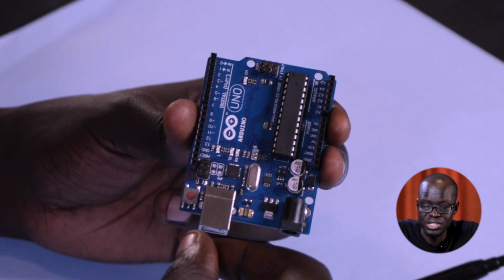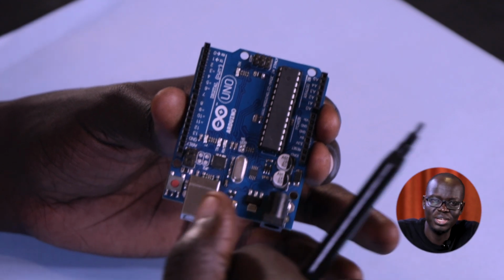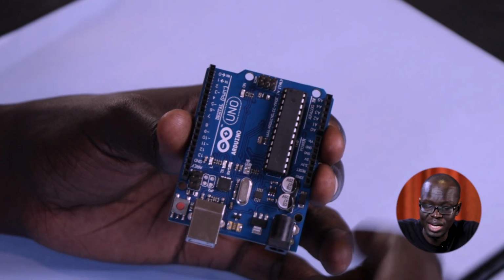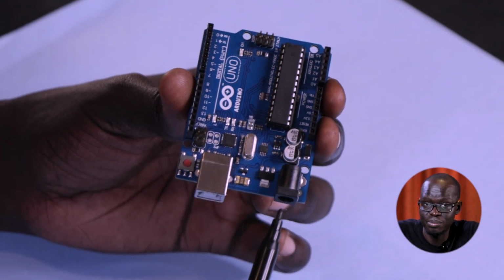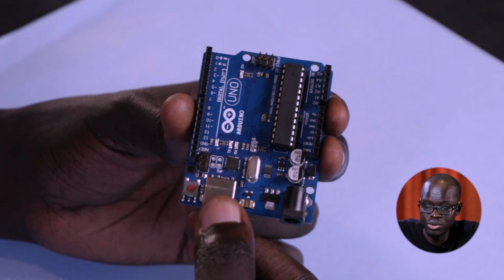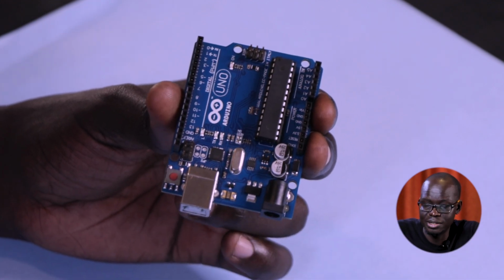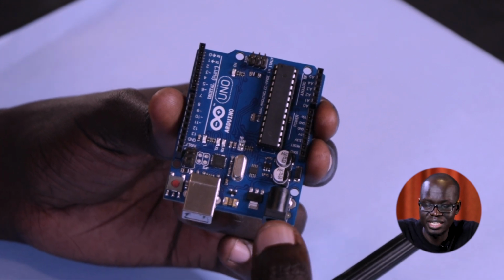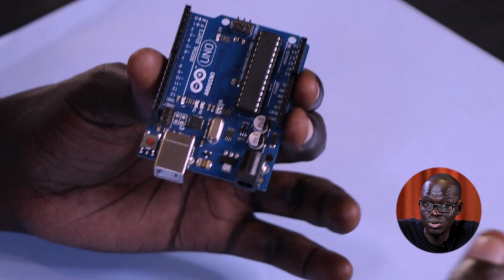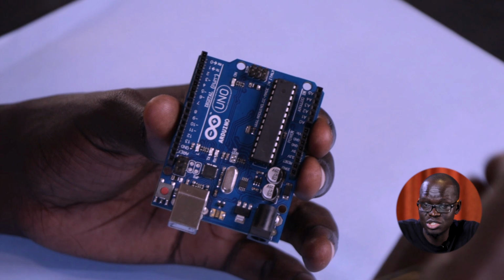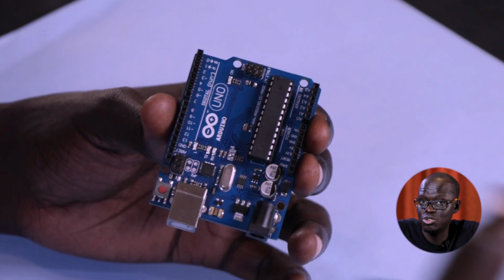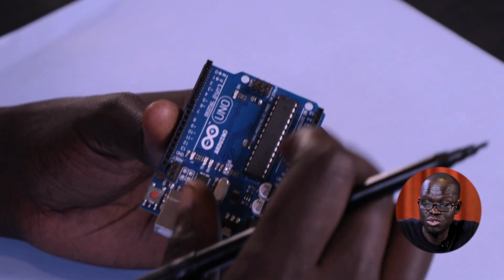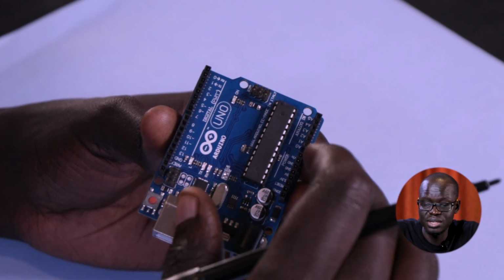If you're working with projects that require low power, like maybe LEDs, some types of devices, then it's fine. But where you can, always make sure that you have a separate power supply here. You can connect both your computer and the power supply, and things will be fine. If you want to connect anything here, make sure that it's an adapter that's giving maybe 6 volts to 12 volts. You can read it on the adapter. It will show you how much power it's supplying, and then you'll be able to use your Arduino board without issues. If you want to use it just with a computer, then you have to make sure that you're running very few electronic components on the Arduino itself.